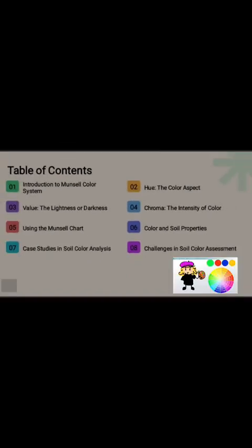Now we are going to learn about the Munsell color chart for soil science. What is the Munsell color chart? It is the visual representation of the Munsell color system, which is a standard way to specify color. The contents we are going to learn in this video are an introduction to the Munsell color chart, hue, value, chroma definitions, color and soil properties, case studies in soil color analysis, and challenges in soil color assessment.